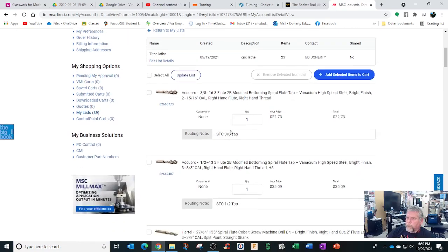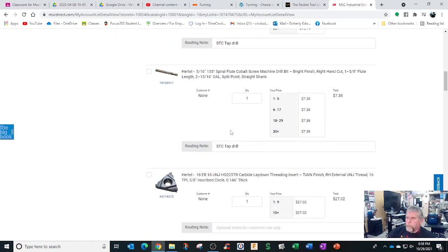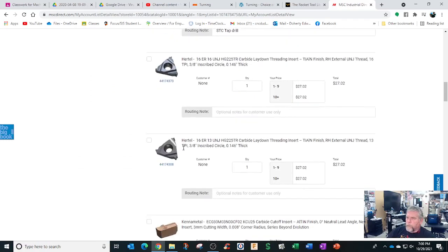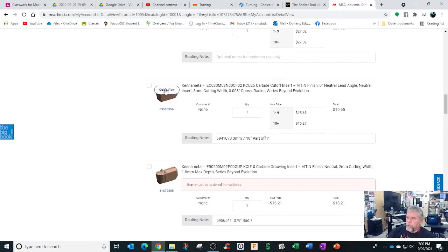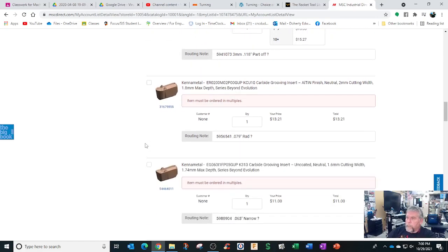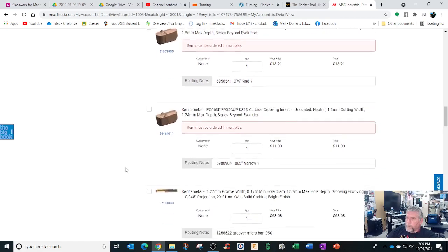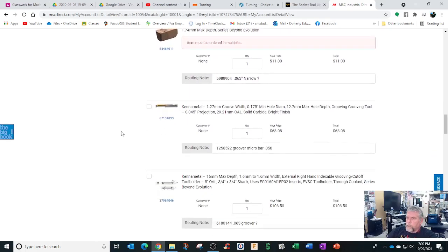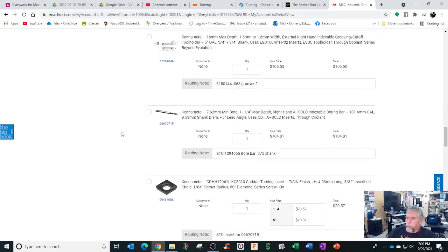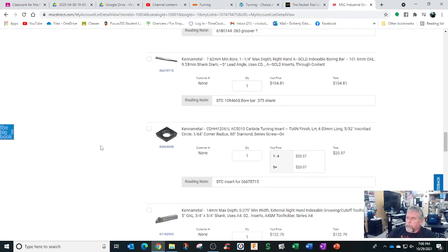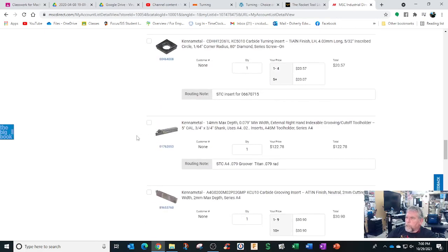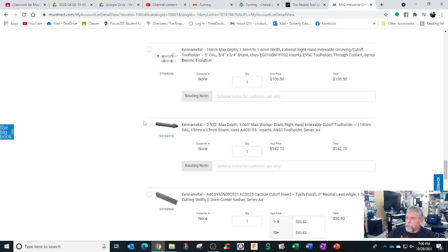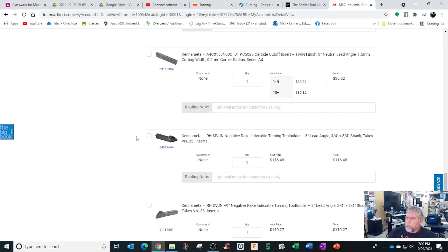We had some other kind of metal tools we decided to keep on using, but we got inserts. We had a different grooving system. We just wanted to make sure we had the right width and the right grade. These are grooving inserts. Internal, we wanted to get the correct boring bar. It had a little tiny insert in there. This is another grooving one. The grooving tool.